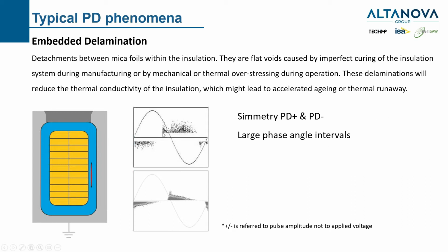When I mean phase angle, I mean the phase angle range covered by partial discharge activity. We have a mostly triangular shaped pattern, and a marked start before the zero crossing of the voltage. When I speak about zero crossing, I mean when the voltage is zero. So in the PRPD pattern, we are talking about angle equal to 0 or angle equal to 180 degrees.